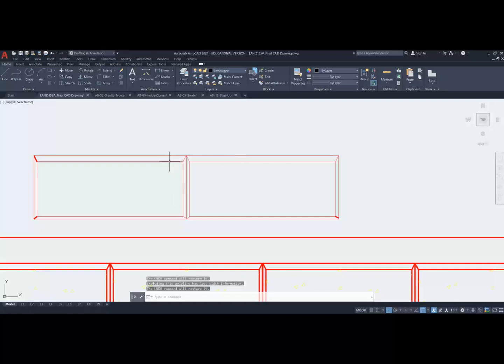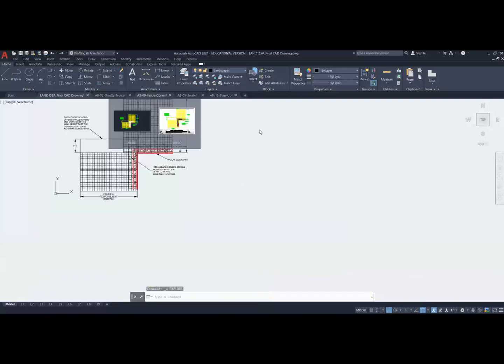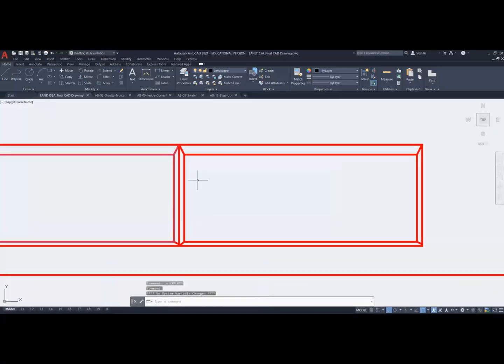There we go. I lost my polyline thickness. Now, I may look at that and say, you know what, I'm going to keep the polylines. If I'm going to keep the polylines, I can't explode it the way I did here. So I'm going to undo it. Or you can say, no, I'm going to get rid of all the thicknesses on all of these things here.